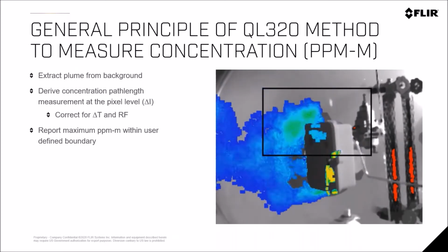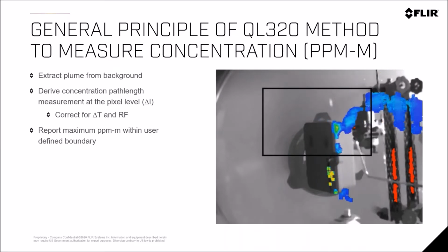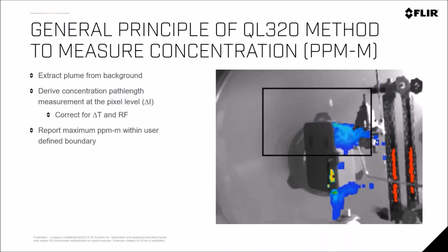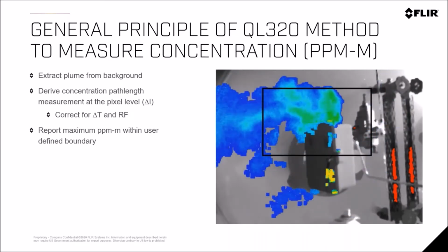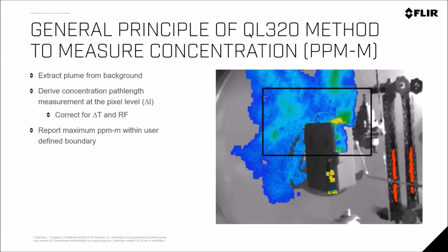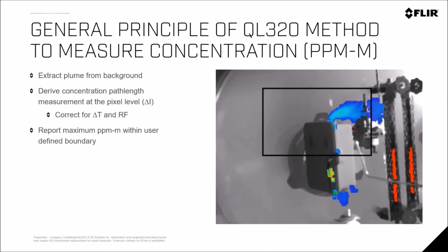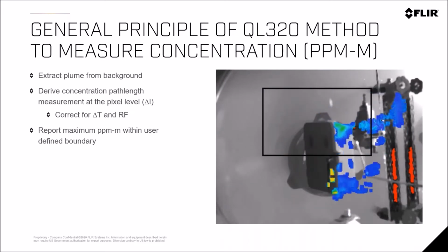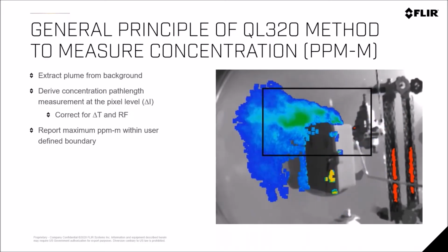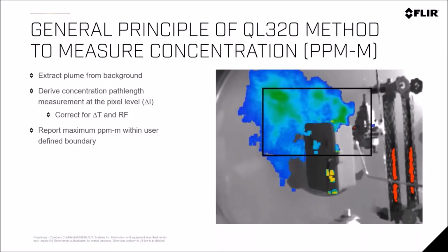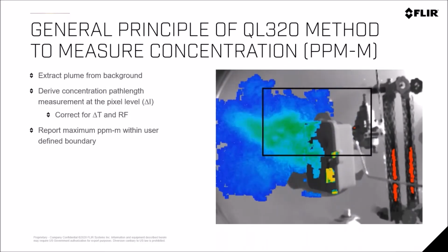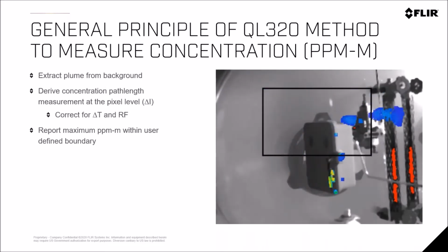In other words, if we could see straight through this video, looking away from the screen that we're looking at, it's assuming that that leak has a 1 meter thickness in the Z dimension, or the 3rd dimension that we can't see in a 2-dimensional video. With that, we're calculating only the delta T intensity and the response factor.